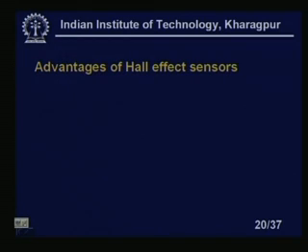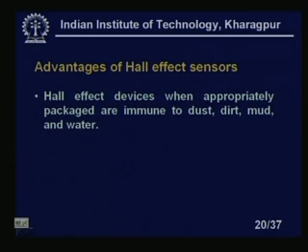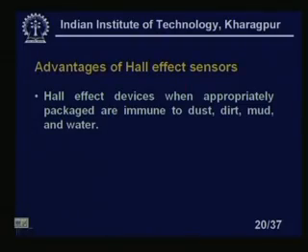Advantages of the Hall effect sensor. Hall effect devices, when appropriately packaged, are immune to dust, dirt, mud and water. In many hostile environments I may use this. It does not depend on how dirty it is, it will work the same. Calibration: I do not have to recalibrate the instrument, that is a great advantage. So in any such environment I can use this Hall effect sensor, especially for the measurement of current.